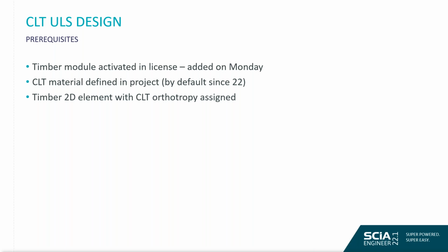Next up, you need to have a CLT material defined in your project, else it will not be possible to run the check. By default, since version 22, there is a CLT material in your project. But if you are importing an old project, be sure to make an extra CLT material, and then you will be able to do the CLT design.